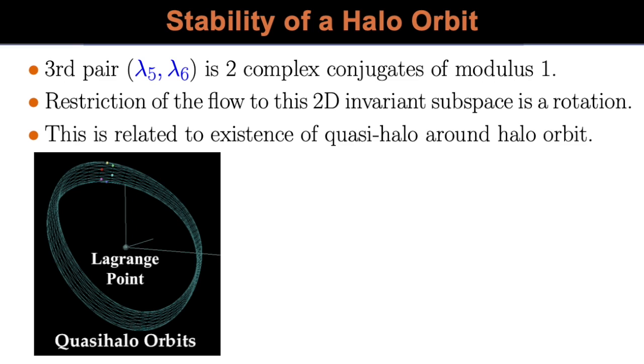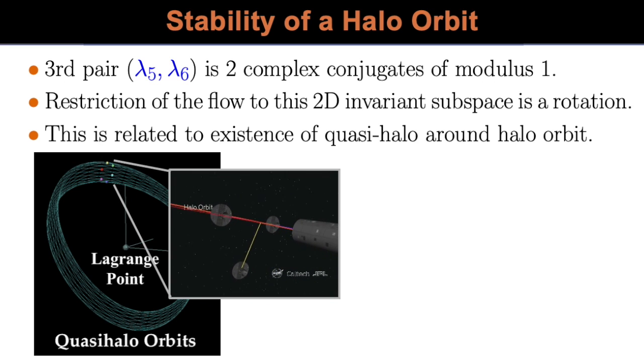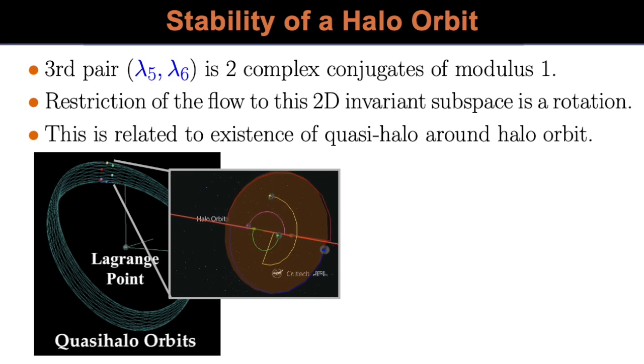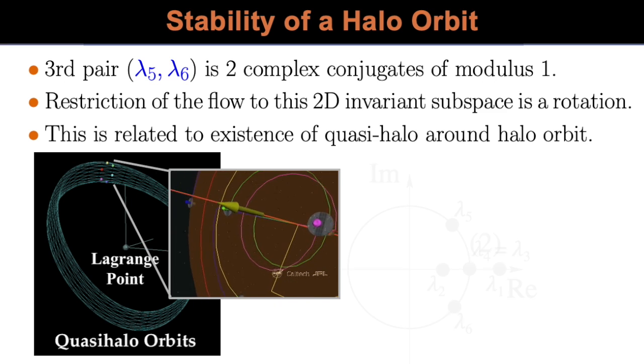So near each halo orbit, there's a whole continuum of, think of them as tori, think of them as tubes. And trajectories, you could do formation flight, things all in the same quasi-halo orbit. In fact, there was some interest in doing this for the terrestrial planet finder mission about 15 years ago. And this is an animation from some of our work back then.